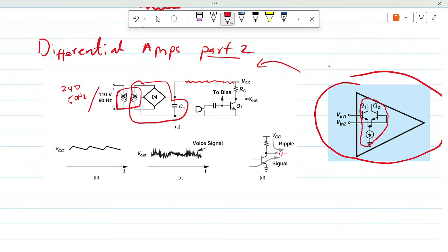Okay, so at our output we might use a capacitor to filter out the DC and get our actual output, which is the small signal amplified voltage. So we have our small signal voltage here, which is properly biased, but this voltage coming from the microphone might be plus or minus 10 millivolts. Basically a sinusoid, where the peak amplitude is 10 millivolts.